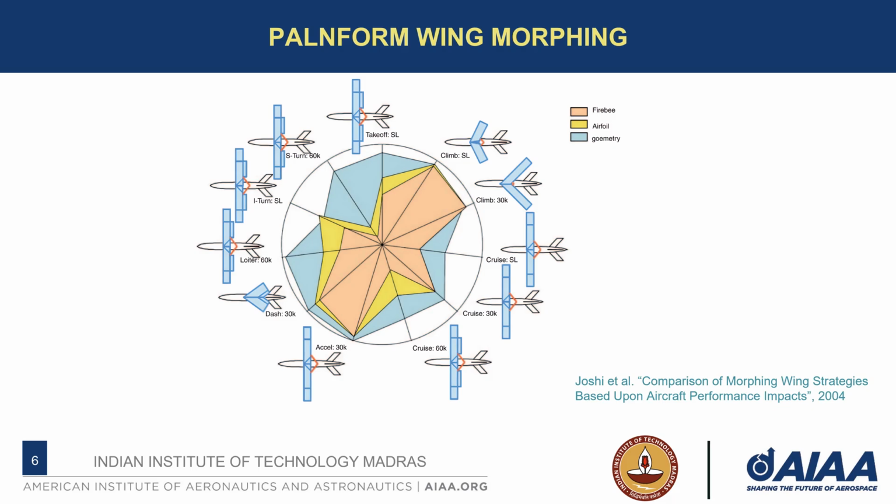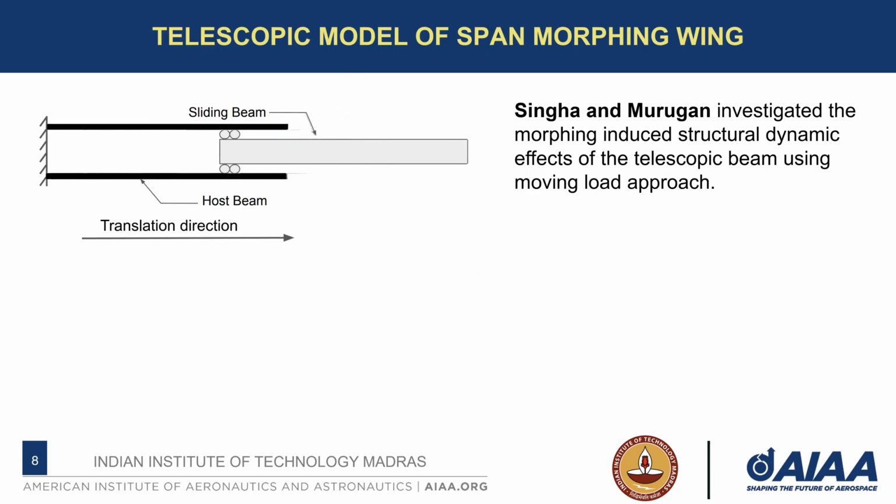However, aircraft that are required to excel at multiple design points see the most benefit from large changes in geometry, particularly when the design points have conflicting goals. Hence, for a UAV, span morphing is a potential solution which can integrate all these benefits of a high-speed, highly maneuverable, low aspect ratio wing, along with the appreciable range and optimal fuel consumption of a high aspect ratio wing. But there are numerous difficulties for designers in designing the span morphing wing.